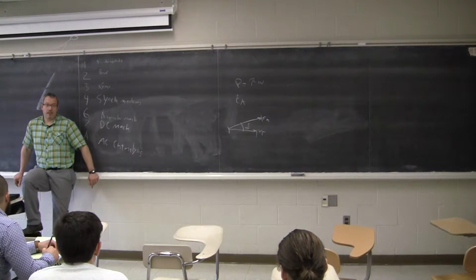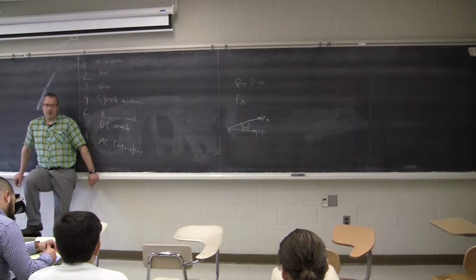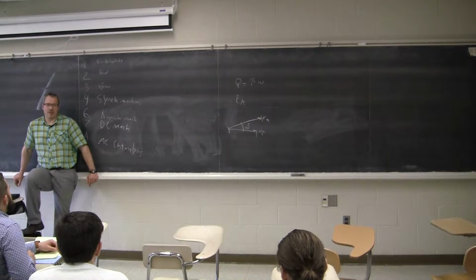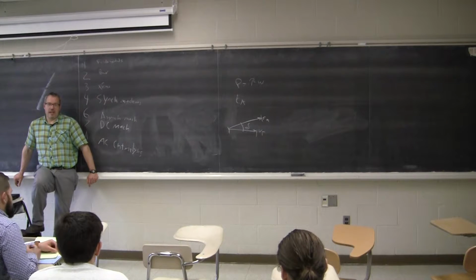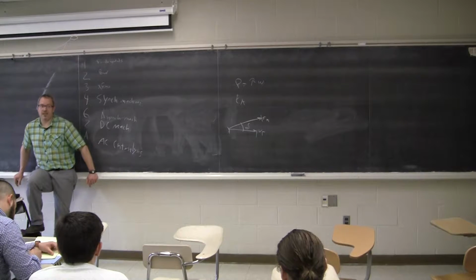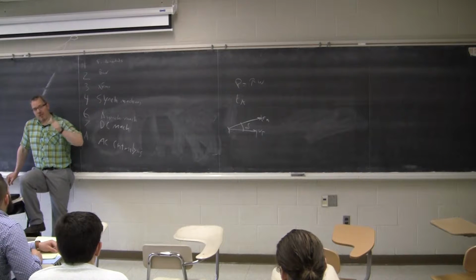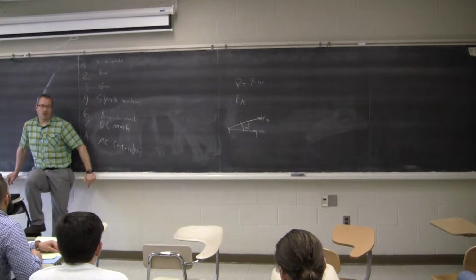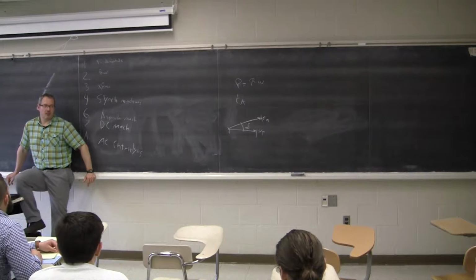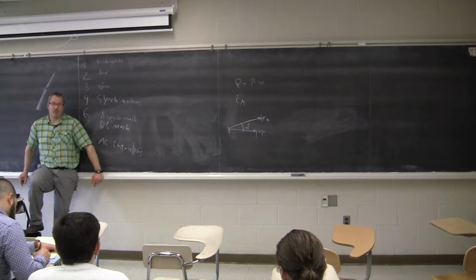In power, it varies a little bit, because when I calculate S equals VI conjugate, if I want to go to 3-phase, now I have voltages and currents which are phasors. So I can't just say it's 3 or square root of 3, but for the individual phases, you just have 3 times those. What monkeys it up is when I start throwing in those line voltages or phase voltages. That's when more complexity gets into the equations. So you just have to be careful about that.